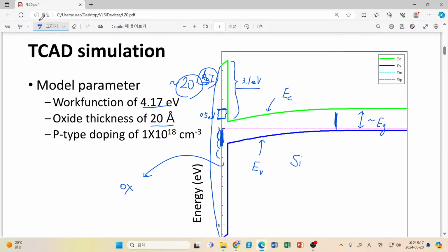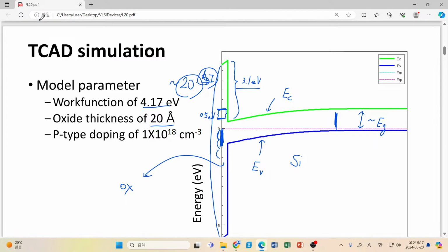So for our usual electrons, actually the energy barrier between silicon dioxide and silicon is regarded as infinitely high. Okay, so therefore it is a really small chance for our electrons to overcome this barrier. So it is good to assume that there is no electron at all in this silicon dioxide layer.